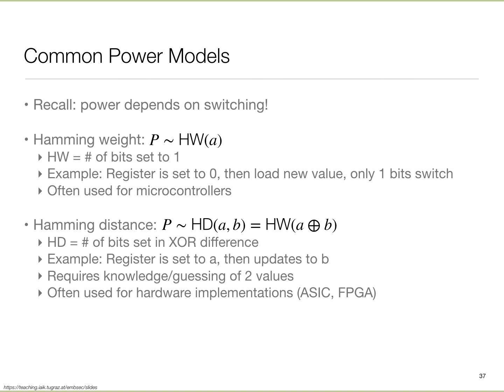But that could be detectable. What you want to do is isochronous computation, not allowing the attacker to see the timing. So I could try to make each one of those rounds have identical delays, but how? Insert no-ops? Is that, for example, what you have in mind? Insert random delays as well. How do you insert random delays?